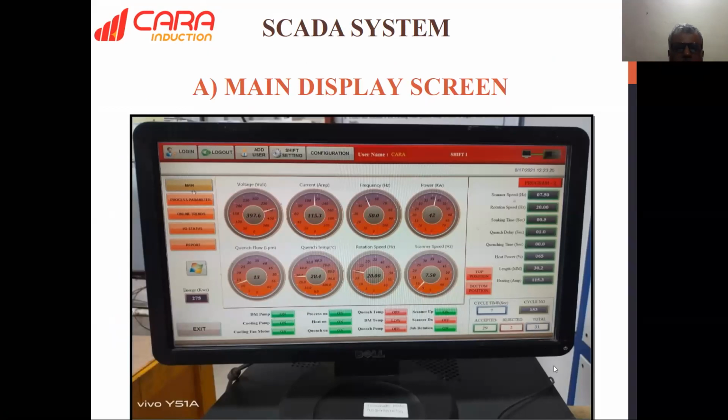And one more thing is that in our induction hardening machine, a SCADA system is required. In the SCADA system, you are controlling the voltage, current, frequency, power, energy in kWs, quenching flow, quenching temperature, rotation speed, and scanner speed. On the right side, there are the machine parameters. So nowadays, the SCADA system is going to help a lot.